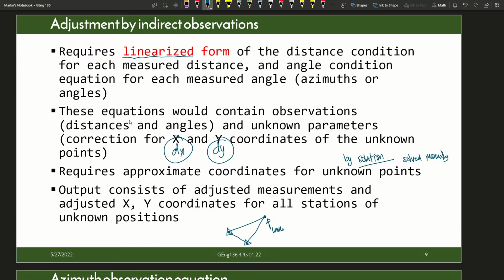However, your determination of this position could be influenced by this line. How much more if you have another line also observing this? How much more like this, like this? So you need to consider this one also. That's why by least squares, in determining this position, we consider all of the observations at once. I mean to say, if we change just this one, it will affect the other observations.